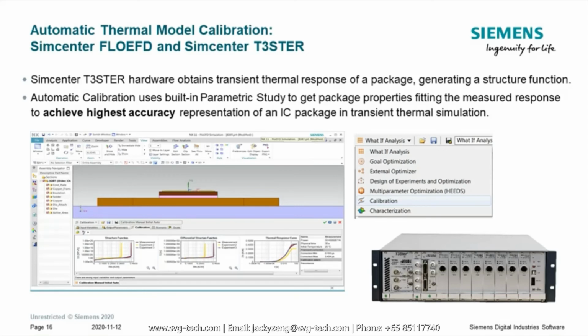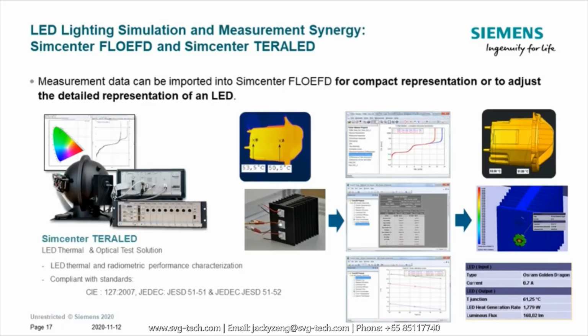If the package on the board is one that you actually have data available for, we have, of course, hardware that does things like thermal characterizations of ICs, like with our Tristor hardware. So if you're using that, you can make use of that data to calibrate your package in your thermal model to give you a higher fidelity model.